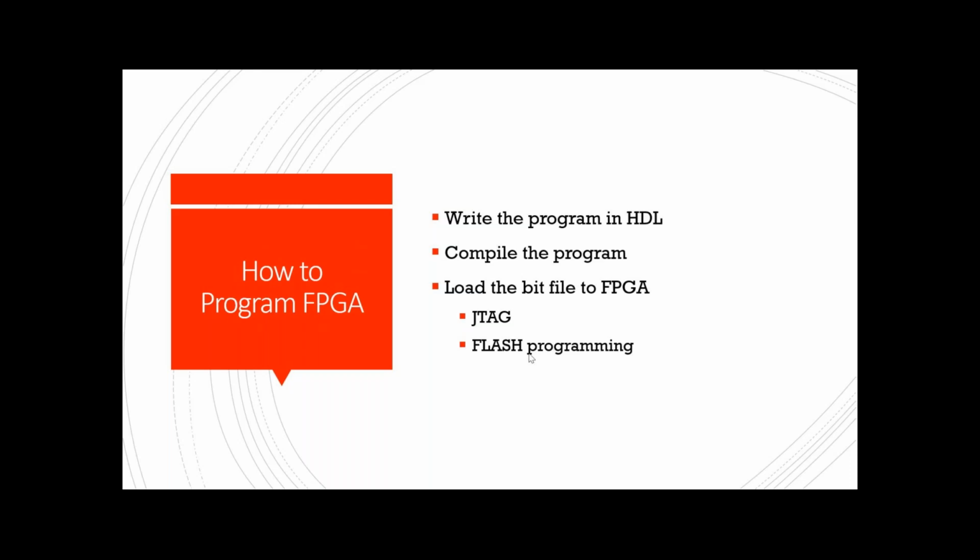Whatever you did in physical design, how to resolve timing violations, the same techniques you have to use here also. You have to go for some pipelining mechanisms and synchronization mechanisms, so that you make the design violation free. Usually we program the FPGA using JTAG or flash programming.